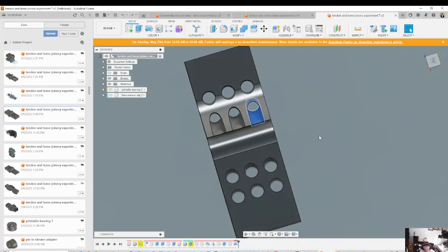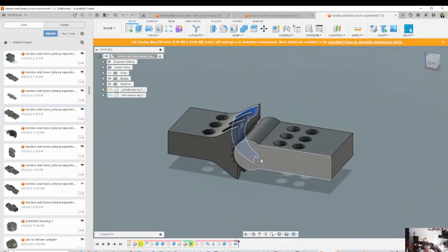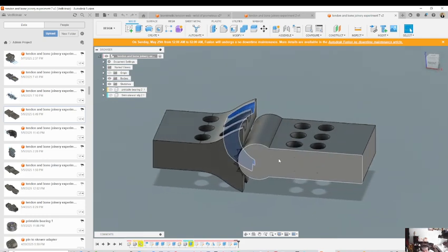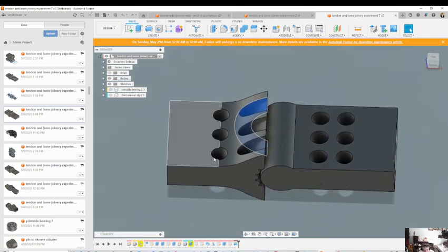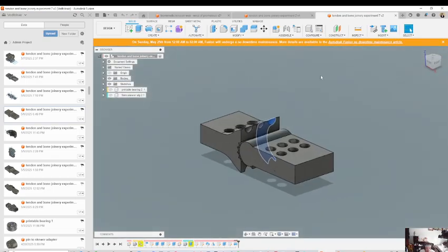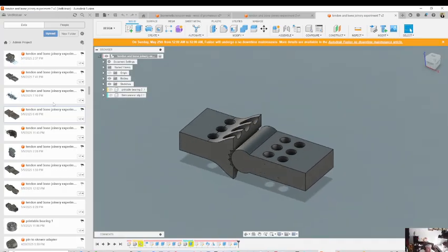I also simplified it to some of its minimum, and so I used 3 here, so to maintain a proper axle. If I had only 1 string to connect those, there would be an issue about spin, since if the joint was not extremely tight, there would be some sway in the thing. Now if I have 3, there's a lot less sway, so this is one of the ways to optimize it. This is a very functional joint, so I could put that in part of a mechanism and it would work super well. I can tie it with the back channels. This is the 7th one, so it took me 7 to get something that was quite functional. Let's go further.